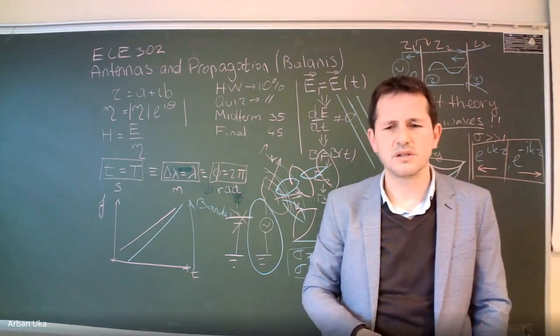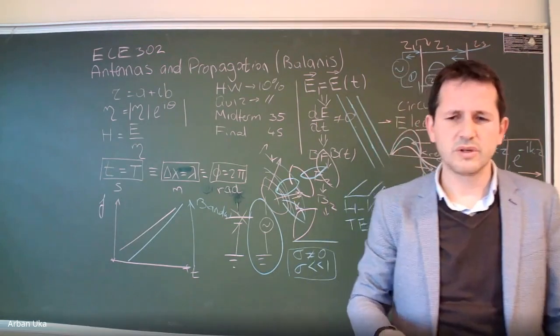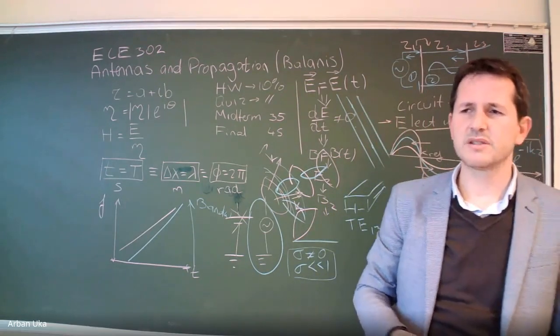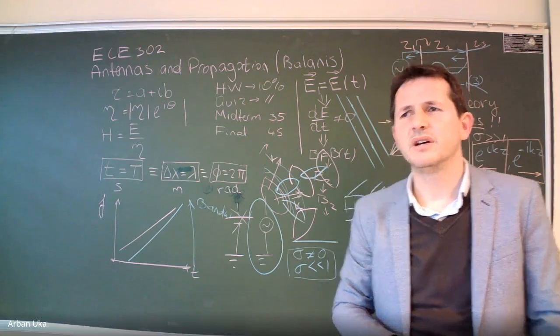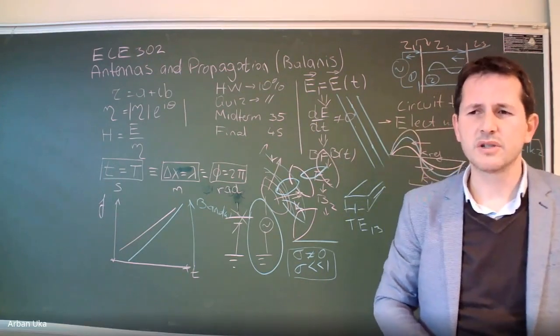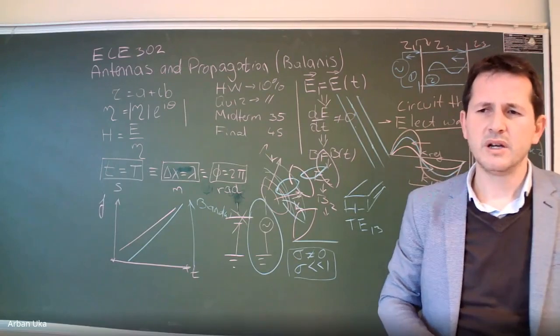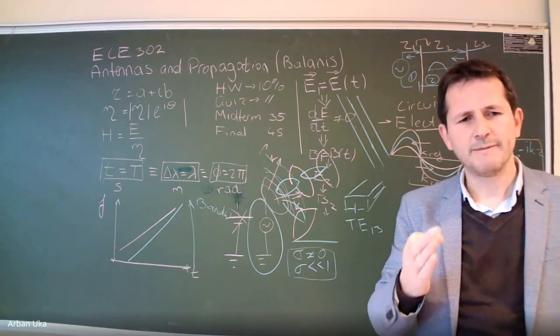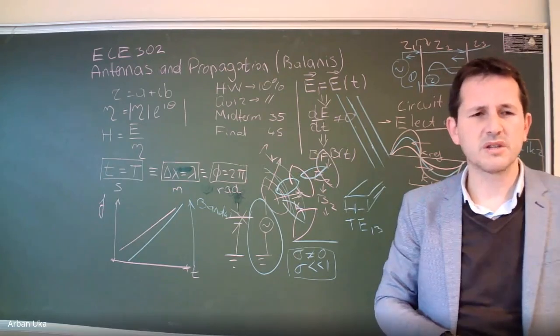Monoxide is more dangerous than dioxide, and we want to have a sensor, and for this sensor we need to design a very highly sensitive analog circuit. But for this highly sensitive analog circuit, we should always be aware that we should have impedance matching between the components of the measurements. Otherwise, you measure nothing.